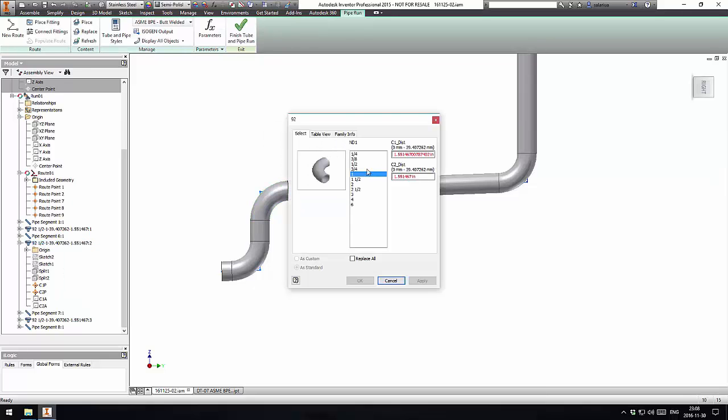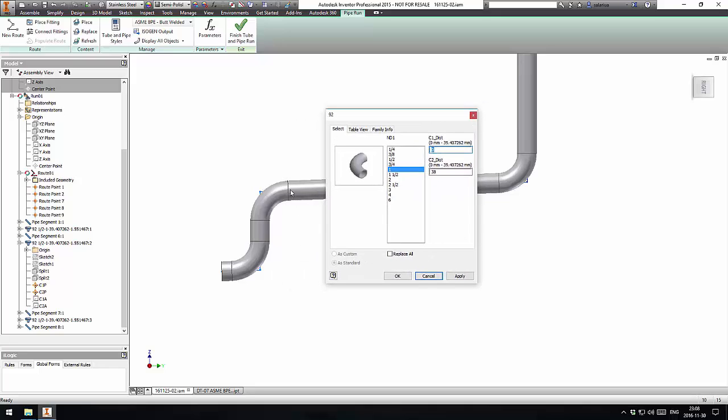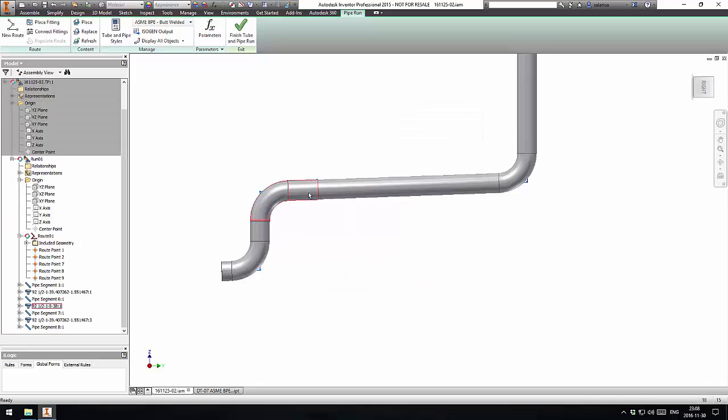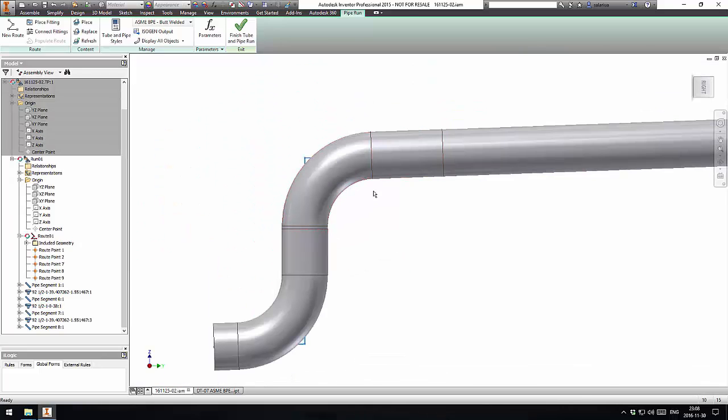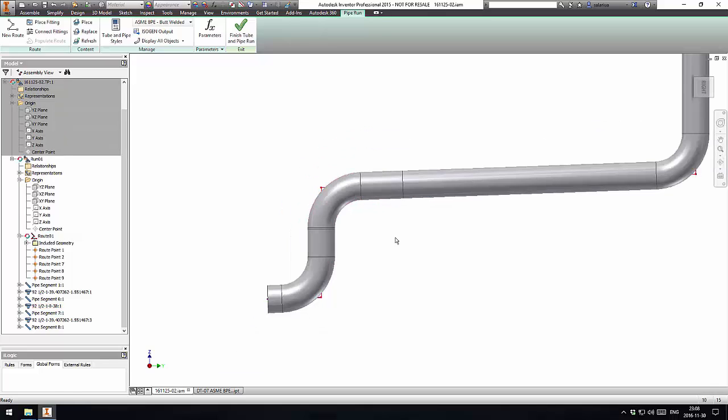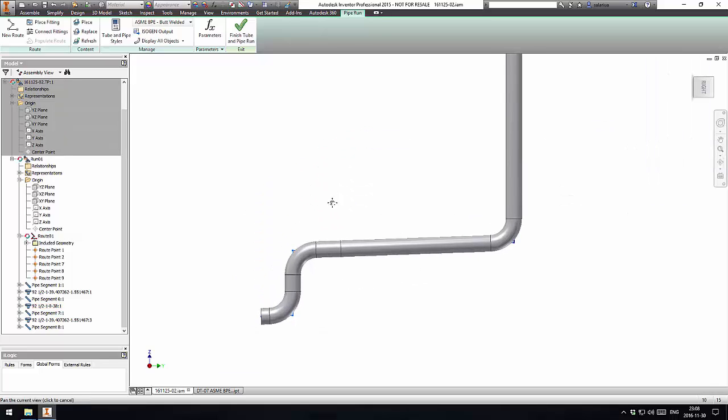Change size. So I've got millimeters and millimeters, even though the value shown is in inches. I'm going to say 0 on the first connection and just say 38 on the second one, and I'll just see what happens. This should be full leg, and this one should be 38 millimeters cut back. See? How's that? So it is working.